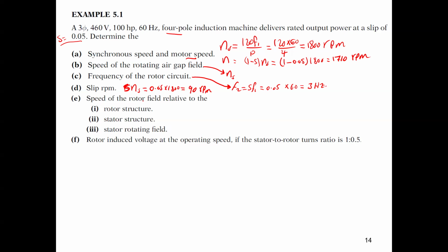All the machine flux is going to move with the synchronous speed. So any flux speed, guys, we have in the machine will be the same as the synchronous speed. Whatever rotor field or stator field, the total speed of any flux is going to be the synchronous speed.